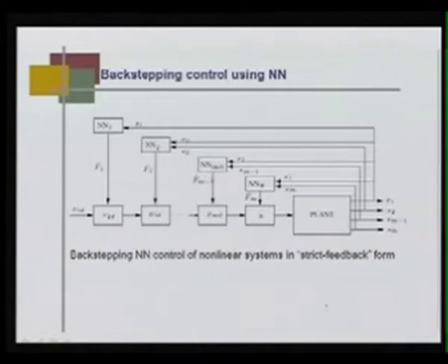So, now this is your backstepping controller. We designed u, and u utilizes the neural network NNm, whose output is fm hat, and it also utilizes xmd, the information given by the backstepping approach, because given x1d, I find what x2d must be.